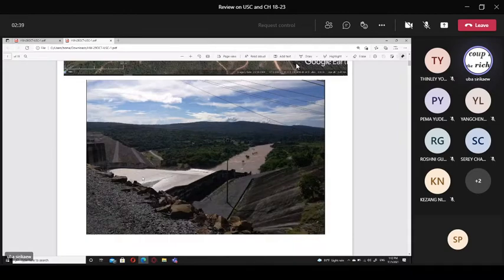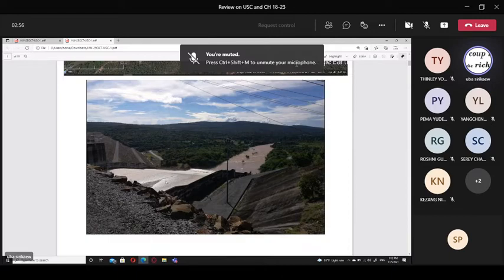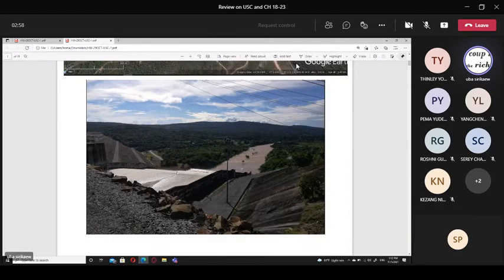So we can reduce the cost of construction. This is the technique we call RCC, roller compacted concrete, for the structure that needs a waterproof front face slab of conventional concrete.